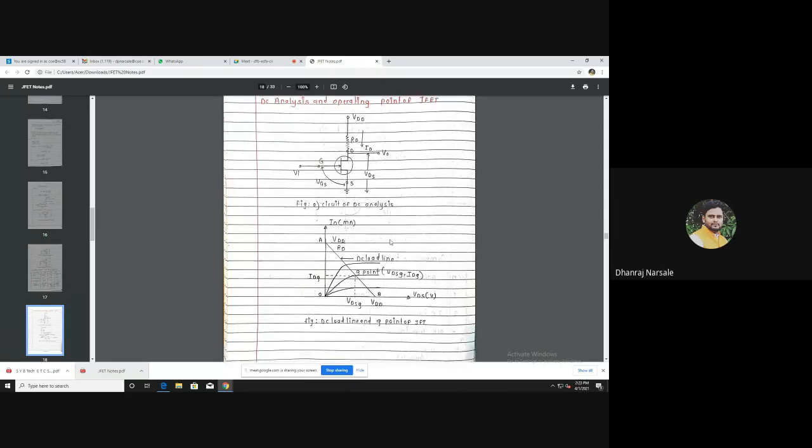Okay, so first of all, you will see here, I have drawn this line AB. Line AB is the DC load line, and here we have drawn the different characteristic curves, VI characteristic curves for the particular JFET. Already we have seen the N channel JFET, P channel JFET. In N channel JFET, the VI characteristic or the drain characteristic of JFET is the curve of drain current ID, in milliampere, versus the voltage between drain and source, that is VDS, in volt, for the different values of VGS.